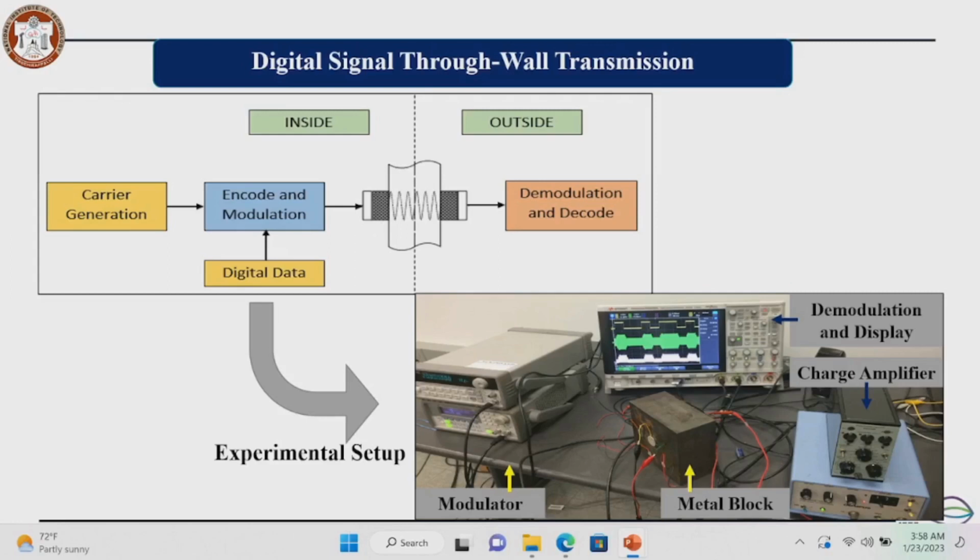It was tested on a different block of metal. Also, different types of piezo crystals were used. These piezo crystals were made for 400 degrees Celsius, and these connections and wires all have a rating up to 400 degrees Celsius. So we connected them, and we changed the demodulation circuit also.